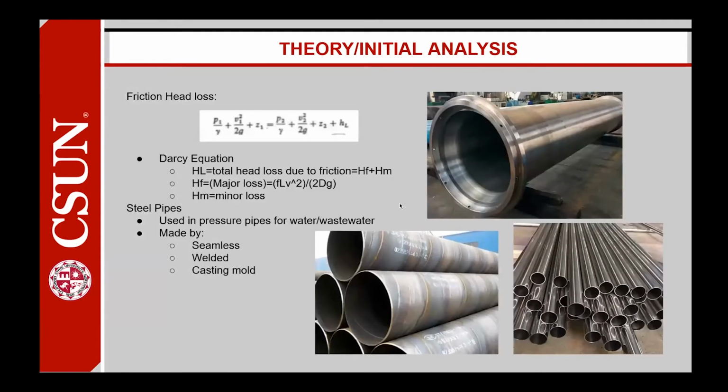Mixing Bernoulli's equation with Darcy's equation, which was also done for us in EPANET, we find the total head loss. With this, we can find the diameter of pipes for our system. Each group used different steel pipes for their project. Some used cast iron, others used stainless steel. But regardless, it seemed that steel was the favorite for its excellent resistance to high internal pressures and pressure surges.